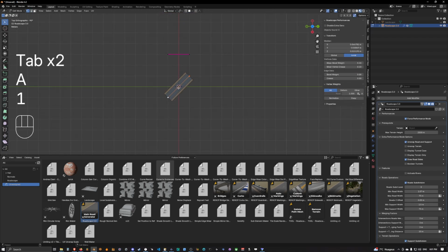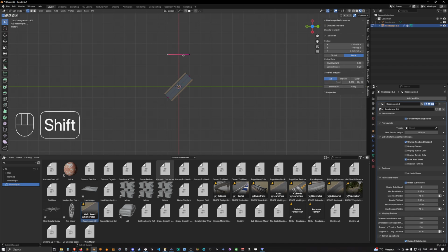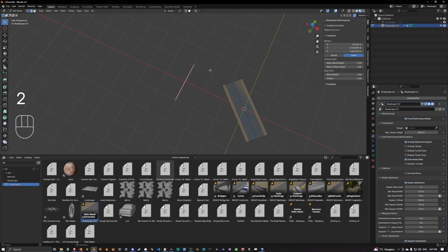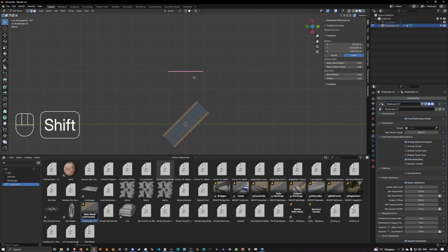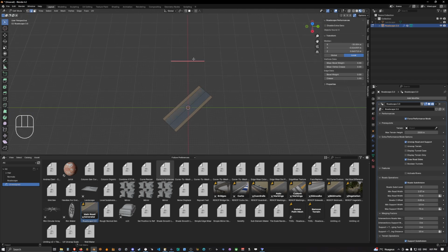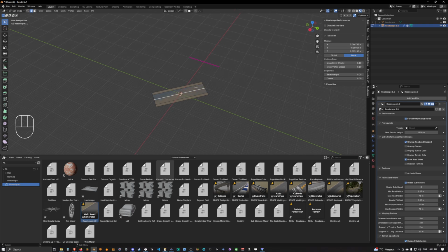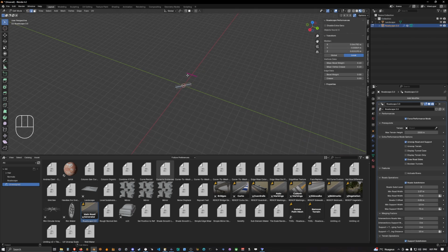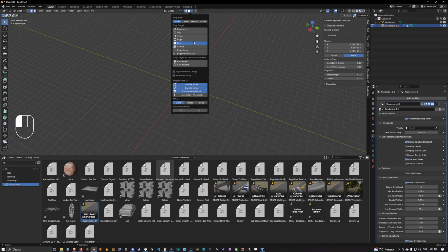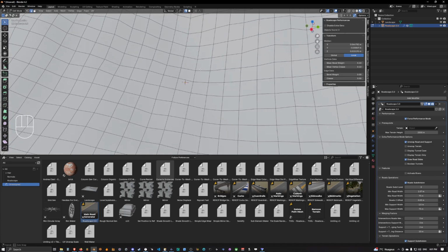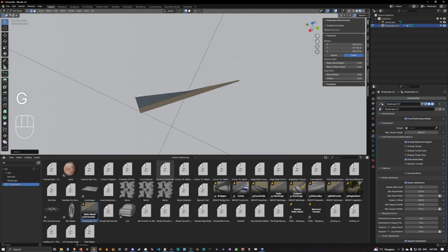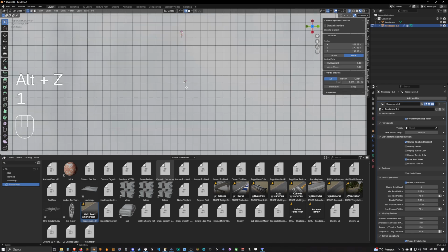We are going to delete those edges. We are going to select only this. Don't pay attention to this. You need to keep at least one creased edge in Roadscape at all times. So this is the reason why there is this. Okay, don't pay attention to this, keep it there. There's no point in doing anything with this at the moment. So we're going to select this, show the terrain again, activate the snap, set to face project, and then we're simply going to move this bit of road onto the terrain.